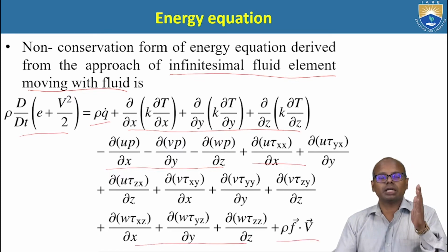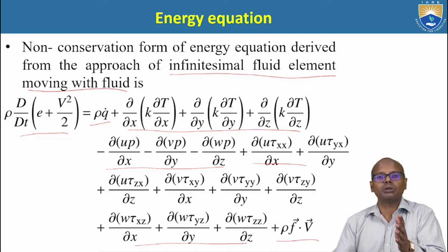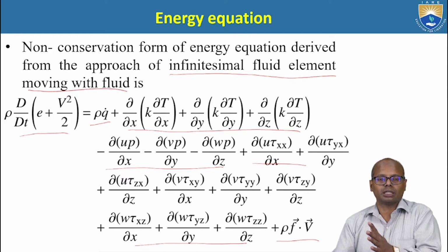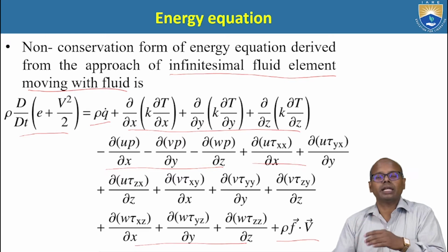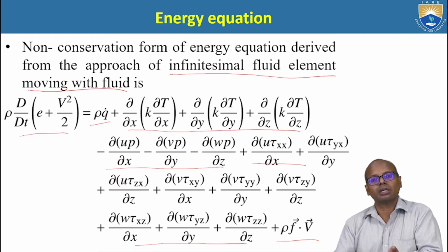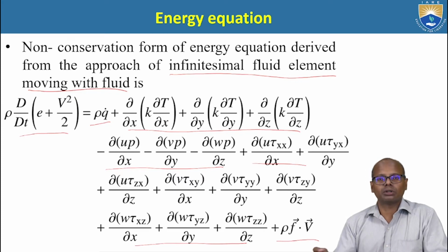So the rate of change of energy of the fluid molecule is equal to the net heat transferred into it by radiation and conduction, plus the net work done on the fluid element by the pressure forces, the shear and normal stresses, and the body forces. This is the equation that we have derived.